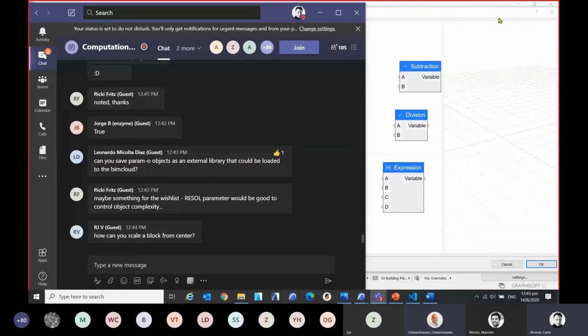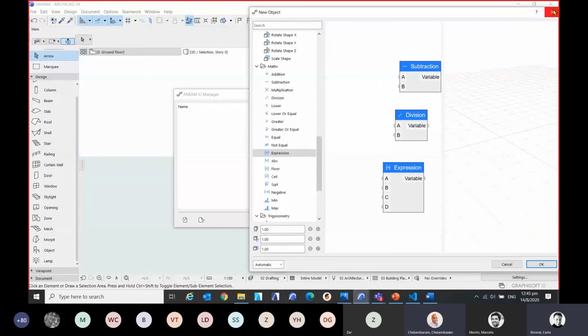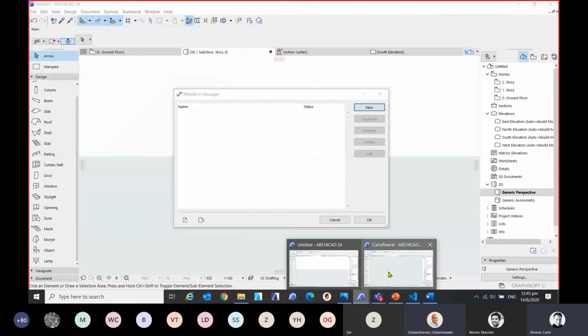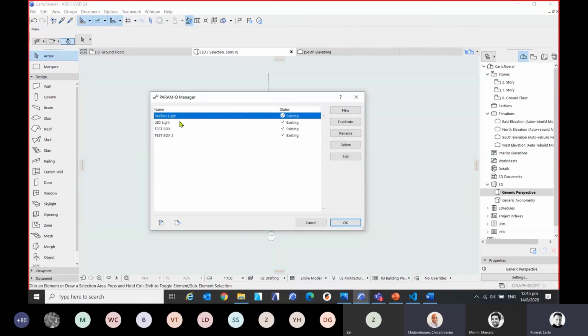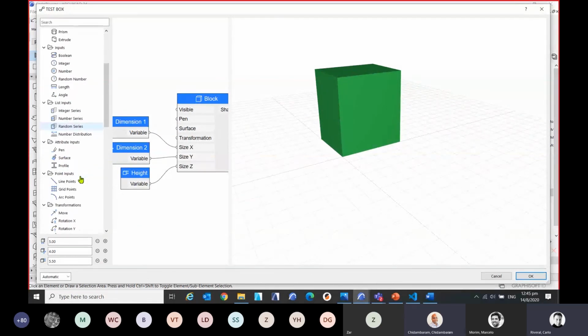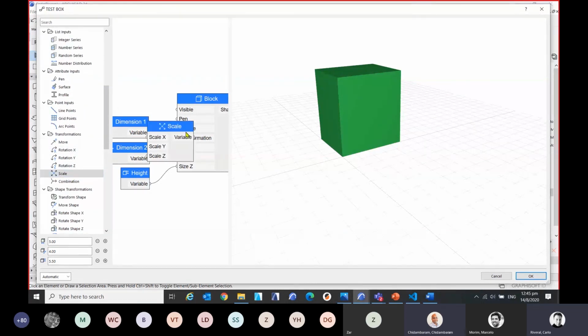You have to move the block by half of the block height to the negative value in all directions, X, Y, Z. Then after that, when you try to scale it, it should scale evenly. So it depends on when you apply the transformation, before or after, right? So then you can actually scale it from the center.